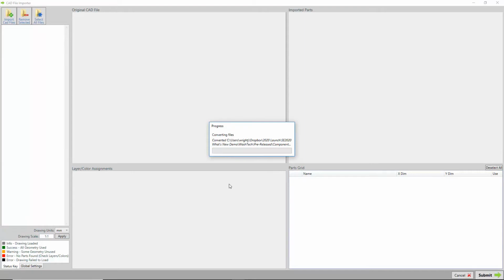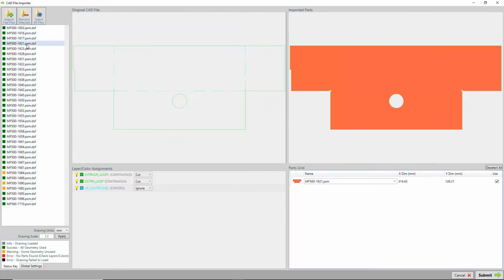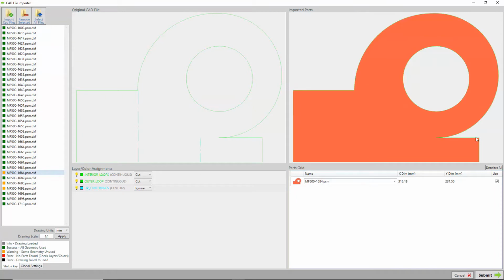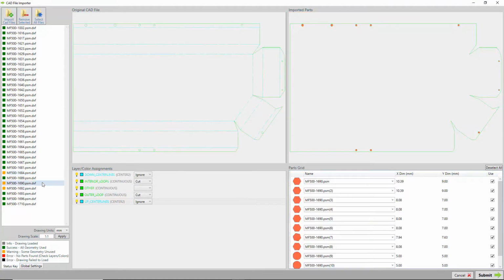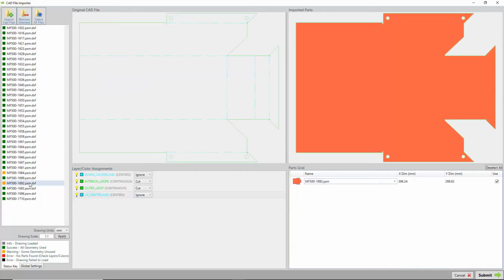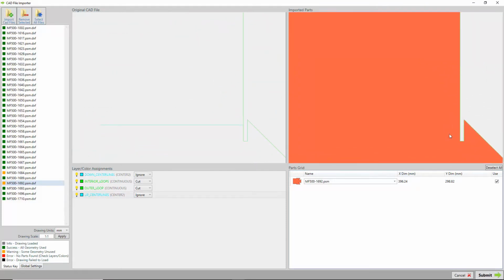The progress bar lets us know that this work is occurring. Another benefit of Solid Edge 2D nesting is that it can extract data from PSM or PAR files. That means it can handle lots of different types of industry requirements. Solid Edge 2D nesting has analysis tools to help us do our job. Each file has an indicator. Let's take a look at the yellow flags. That part's okay, but this part has a real problem where the edge of the sheet metal part has been chamfered. We'll discuss this with the engineer, but for now, we'll remove it from the list. The last file has a very small notch in it. That could be a problem, but for a water jet machine, that's okay.